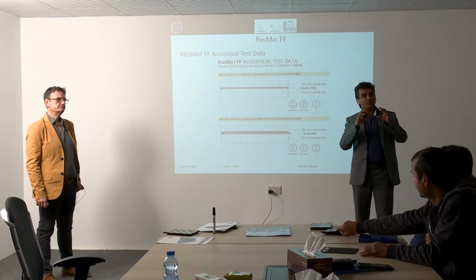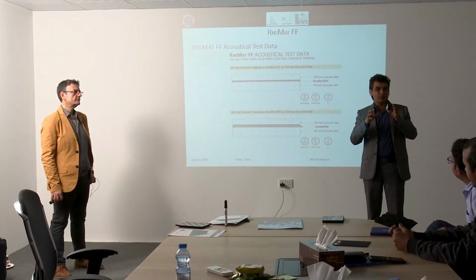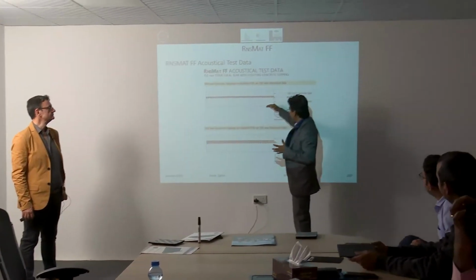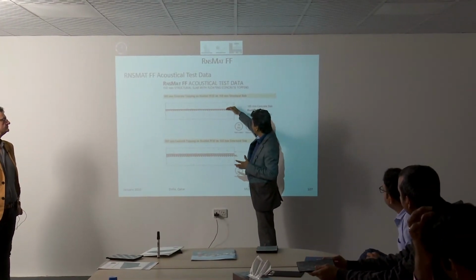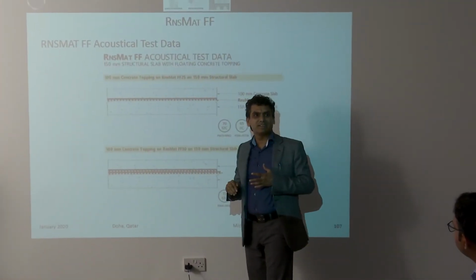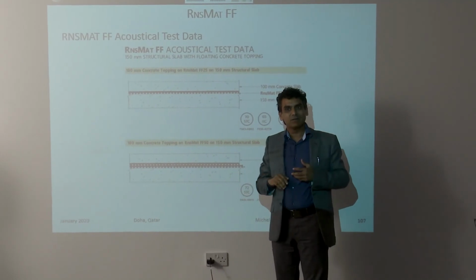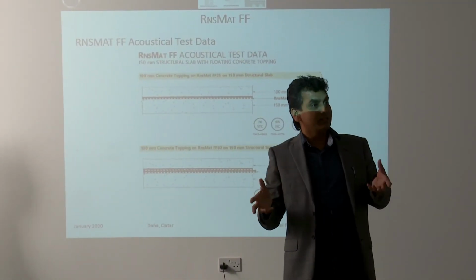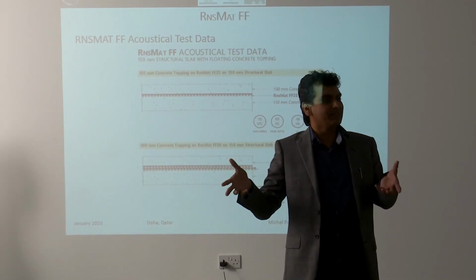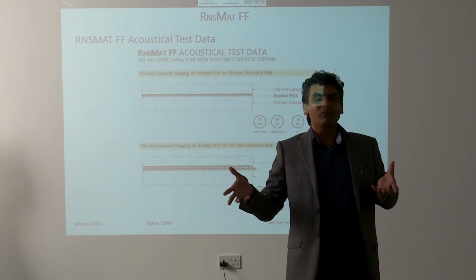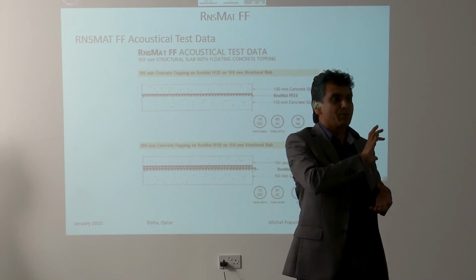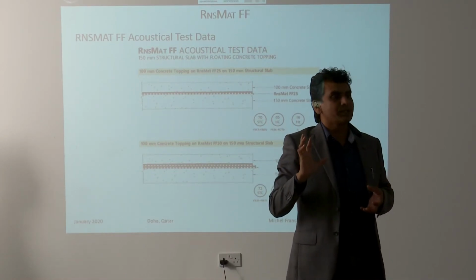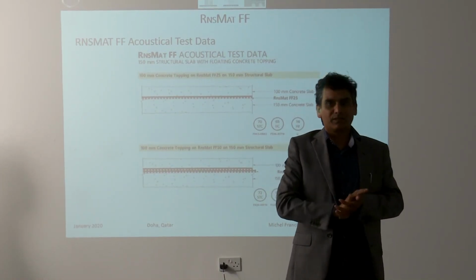Because see, I tell you, we are proposing now in UAE: underlay, floating floor, underlay. It will be more costly, sir. Yes, but particularly in this contract it is costly because they need a solution, because the chiller equipment is very heavy. For chiller equipment and certain specific cases; I am not going to propose it on every project. It is going to be project specific.